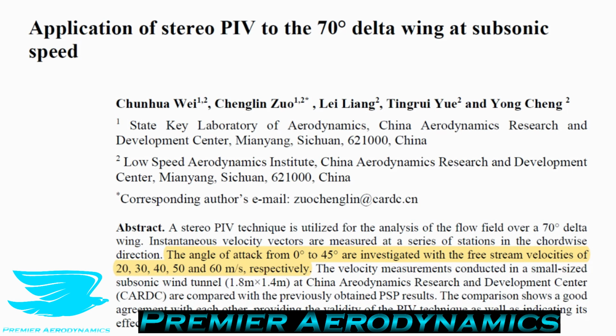And what this is, you determine what the velocities of the flow are using lasers and cameras and seeding particles. So what you do is you dump a bunch of seeding particles into the flow. Ideally, these particles will follow the flow well, so that you call that faithfully. That means that when you have even high rotation areas, these particles will still follow that. And that depends on the particle size and density and that. So I'm not going to go into that. That's just a regular PIV.